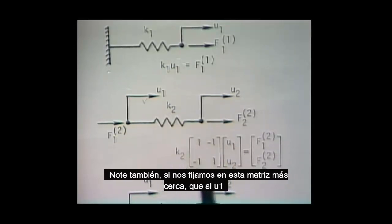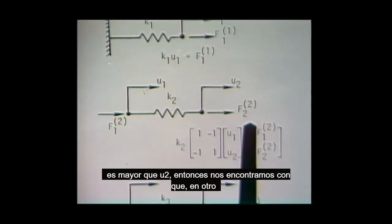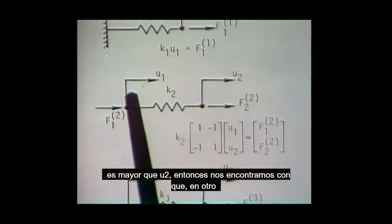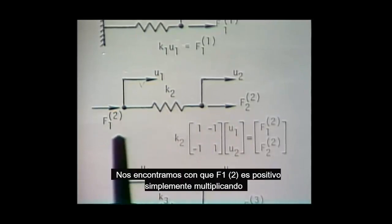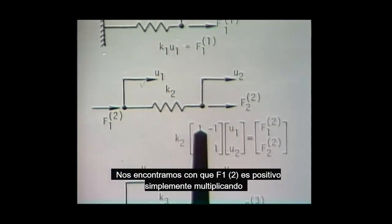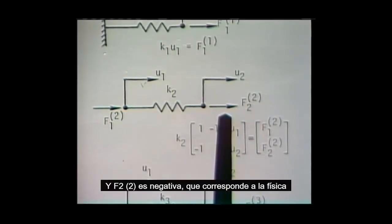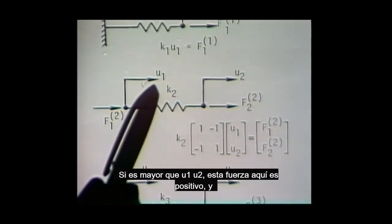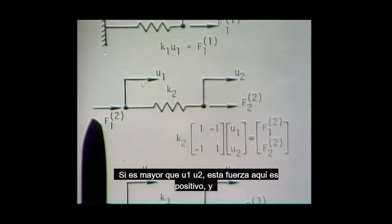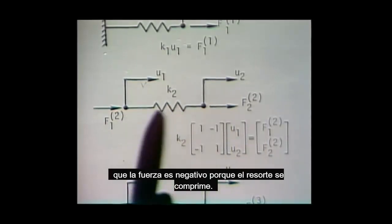Notice also, if you look at this matrix closer, that if U1 is greater than U2, in other words, U1 greater than U2 means that the spring is in compression, we would find that F1² is positive by simply multiplying this out here, and F2² is negative, which corresponds to the physical situation that we actually have. If U1 is greater than U2, this force here is positive, and that force is negative because the spring is